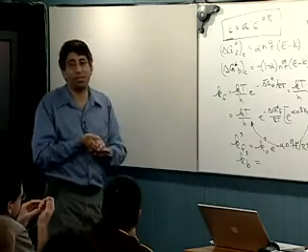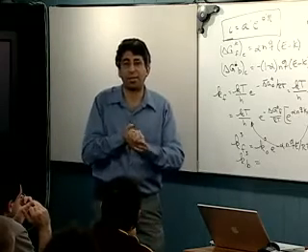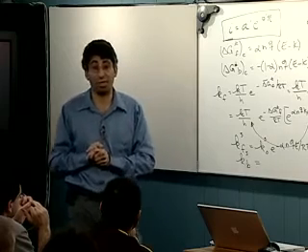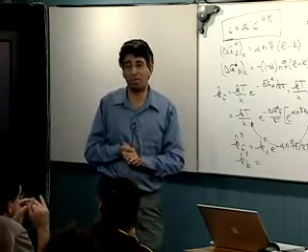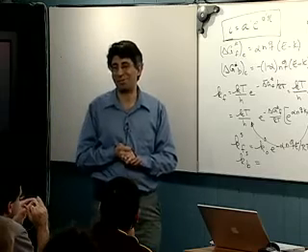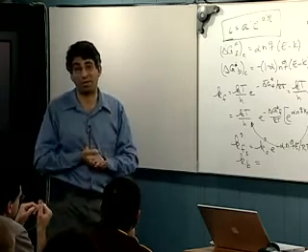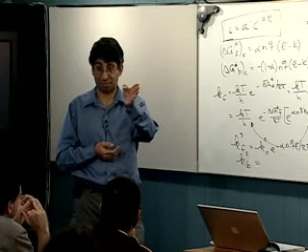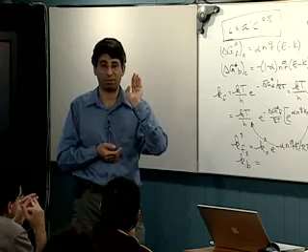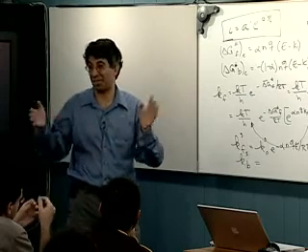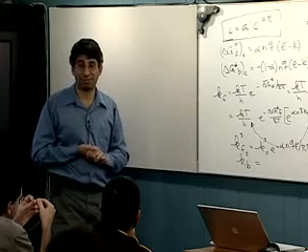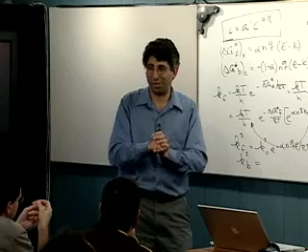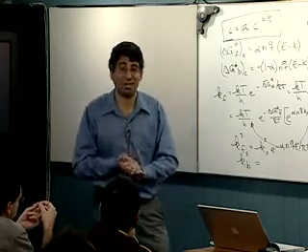It is easy for us in our labs to generate between 10 and 20 amps. That's not an exaggeration of current in a fuel cell that has 1 square centimeter, 5 square centimeters of active area. 1 square inch of active area in our absolutely best cells will get up to 20 amps out of that cell. And on our kind of OK cells, it's still at 10 amps. So we actually have battery cables coming off of our fuel cell to take care of the current. We have these huge currents that are coming out.